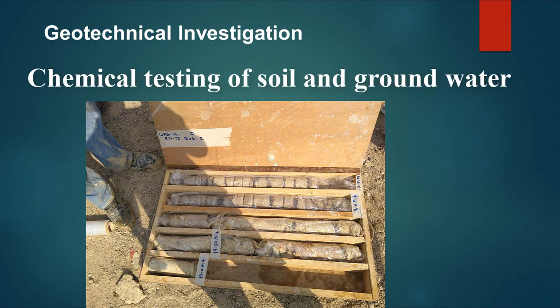Soil and groundwater chemical analysis. Chemical analysis shall be conducted to determine the chemical composition of soil and groundwater. The chemical composition can affect the selection of concrete and reinforcement type. For example, if the sulfate concentration is high, the selected concrete for the foundation shall be sulfate resistant. Sulfate can adversely affect concrete by causing expansion of concrete, and this will lead to cracking and spalling of